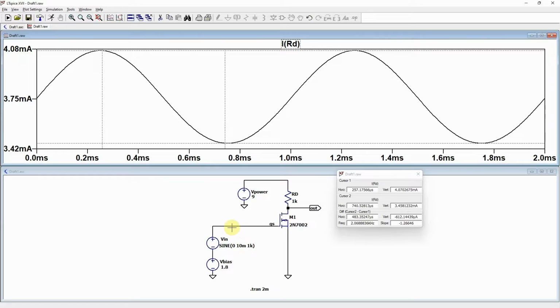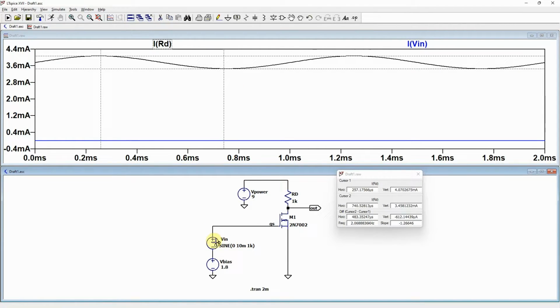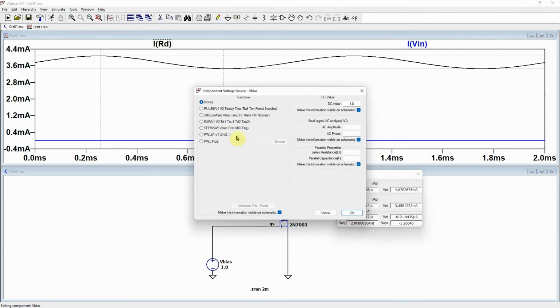So with this MOSFET, what we're trying to do is figure out how the current changes. So I'm going to come in here and delete this off and just create a variation here. We're going to make this a pulse, going from my cutoff to about 1.9.